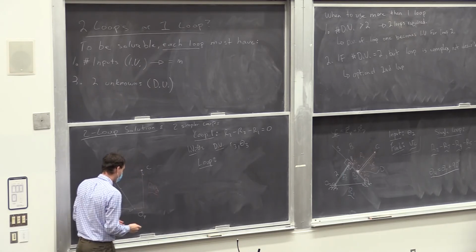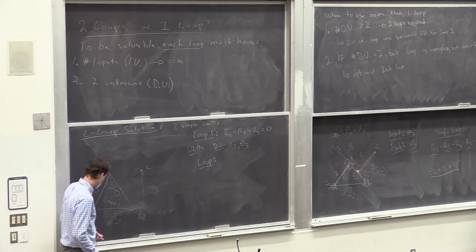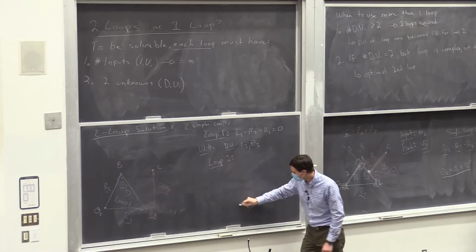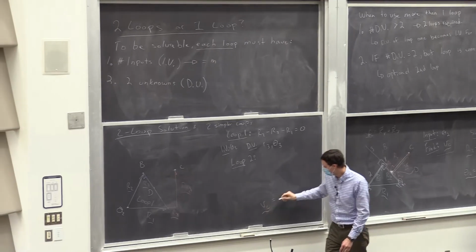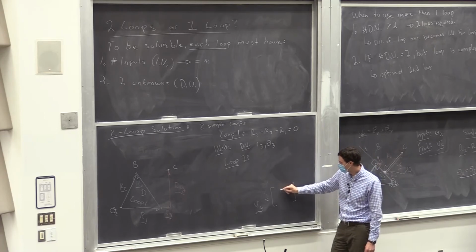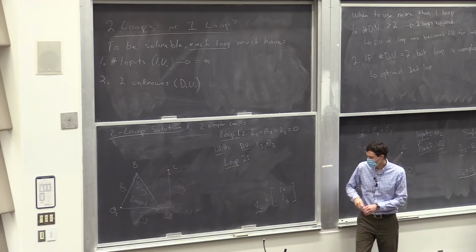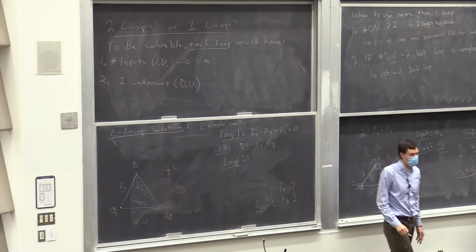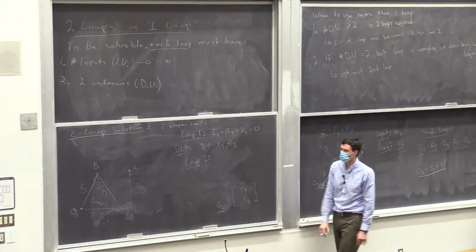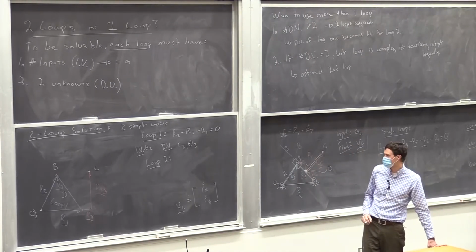And I'll call those just Ry and Rx. Okay, and that is going to have the great advantage that we can write velocity of C. It's just going to be x plus y. So Rx dot and Ry dot. And those are things we can solve for directly. Our loop equations, those will be dependent variables. We can solve for them. It's just the length of vector x and y. Solve for them directly, and we have our answer without that additional interpretation step.